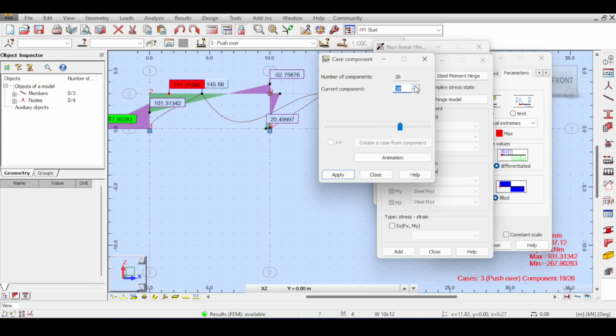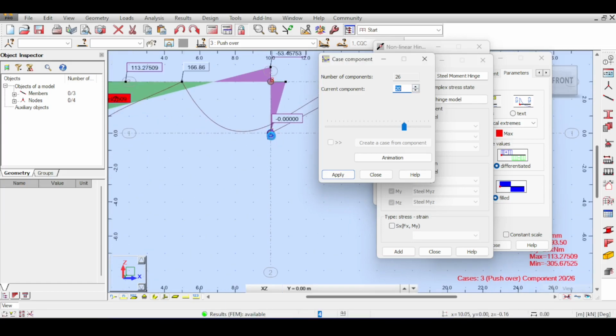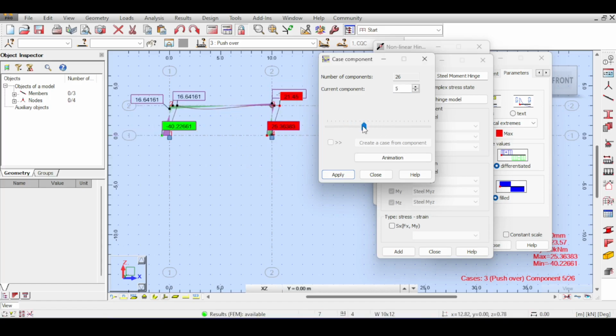Now, what do I get from this after I see this? I get from this that point number 4 is the first point to snap, and I know that this is now the weak point of the structure. The failure will commence from here. And of course, you have to do a deeper analysis for the type of failure mode that you would have once point 4 snaps.